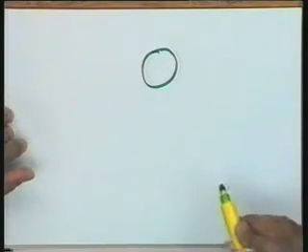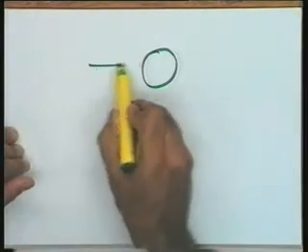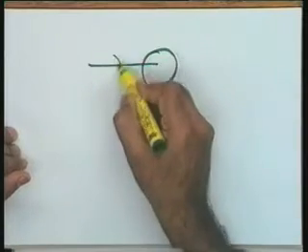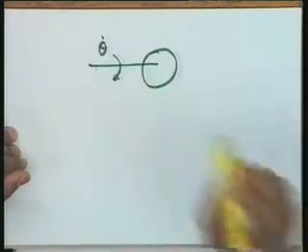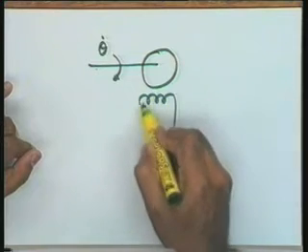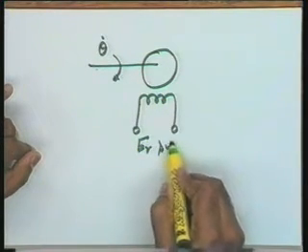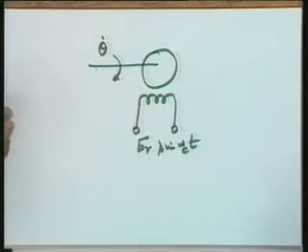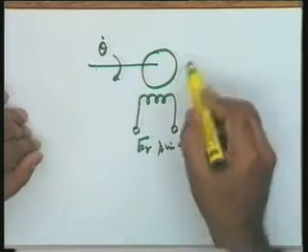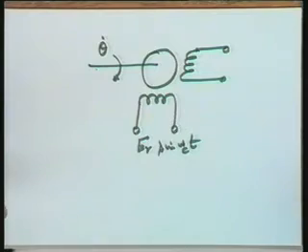A quick glance at the tacho generator also should be helpful at this stage. The tacho generator, what is the input, please? The input is speed, theta dot. Okay? Let me say here I have a reference winding, and Er sin omega_c t I take as the input to this reference winding. The output here is again going to be a modulated signal.